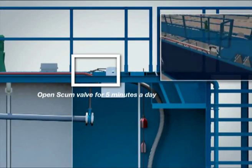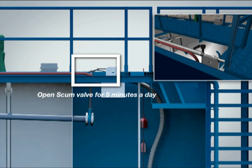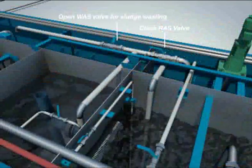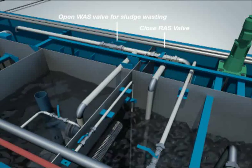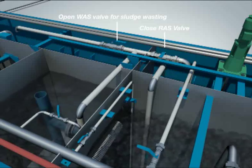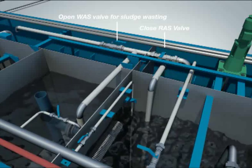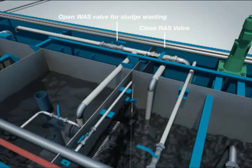Open the scum valve for 5 minutes a day or until top of clarifier is clear so that the scum floating on the clarifier will be recycled back to the EQ tank. Close the RAS valve and open the WAS valve for 15 minutes as often as advised. The frequency of this operation may vary for each unit and will be advised by the visiting process engineer during the weekly site evaluation routine.